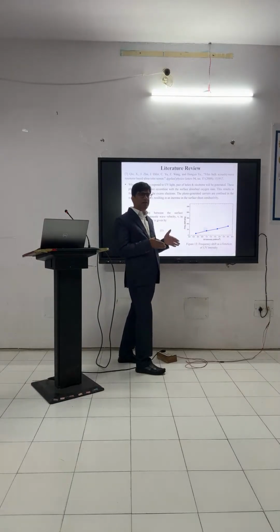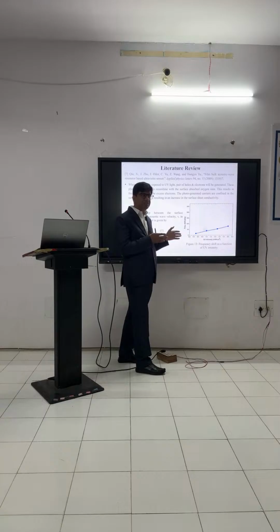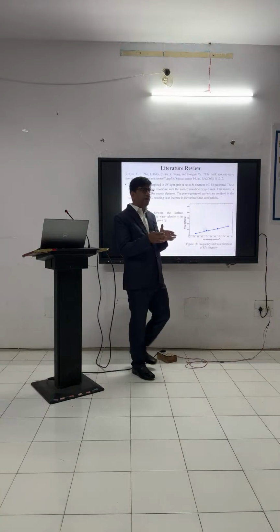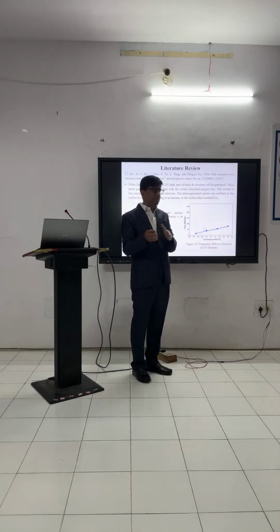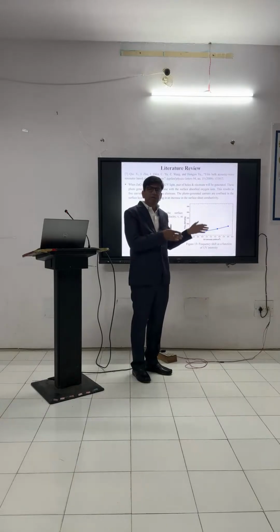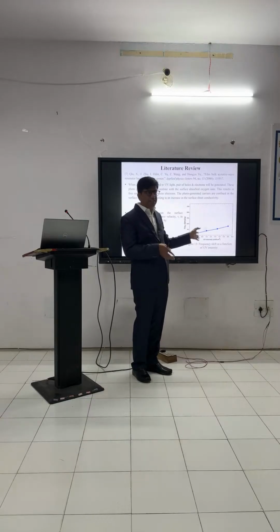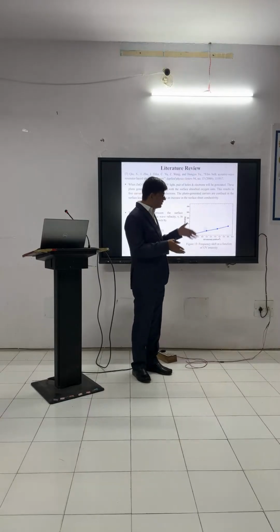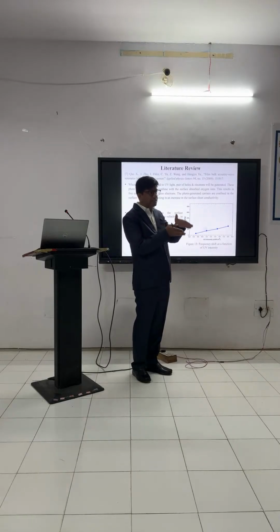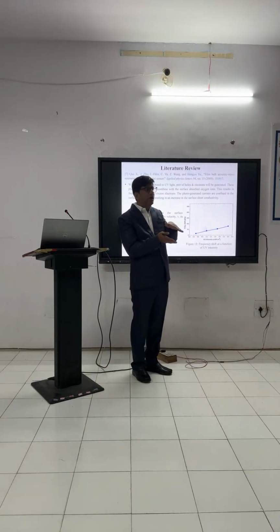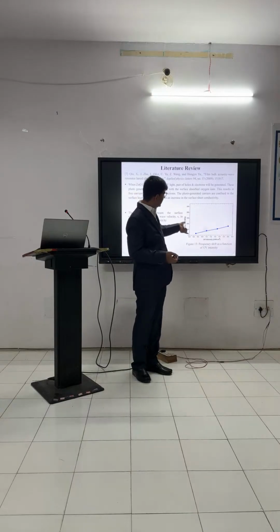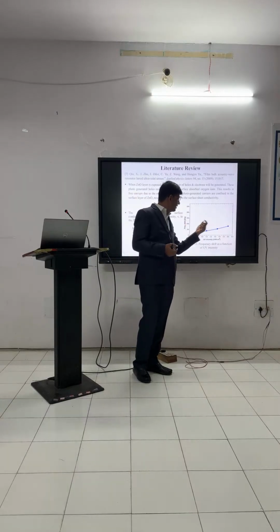So the output in this UV sensor is a change in the frequency only. Like that, if you have a MIM sensor or thin film transistor, what we have as output is a change in the current according to the change in the quantity being sensed. Here, instead of change in current, we have a change in frequency. So that's why we correlate this change in frequency with particular UV exposure. Clear? So we will measure change in frequency for different intensity of UV.